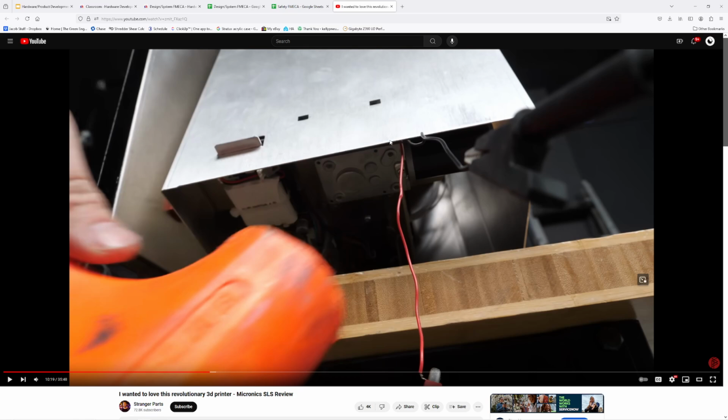So basically, they have this auger at the bottom, right? And it's just a regular DC worm gear. Here's the DC motor right here. You can see the front end and rear end cap and the black housing in the middle. And then there's an auger that goes up and sucks powder in. The problem he's having is that it is getting jammed at the bottom. The packing density is so high because you have these different particle sizes that it's just caking up, and this auger is struggling to overcome it.